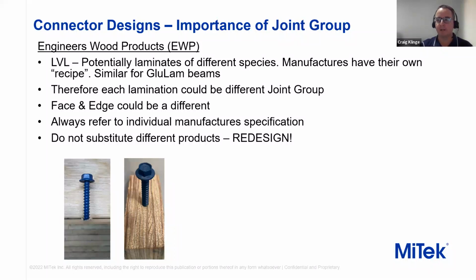As nail plate suppliers, we also do a fair bit of independent testing with regards to our plate grip across both sawn and, more importantly, EWPs. The tooth group with the EWPs is very specific to each individual LVL product. So every product that is available on the market and used in software, we've tested for the grip, and they've all got their own specific properties.